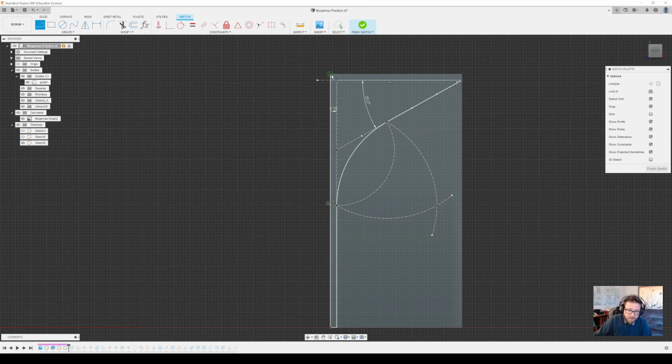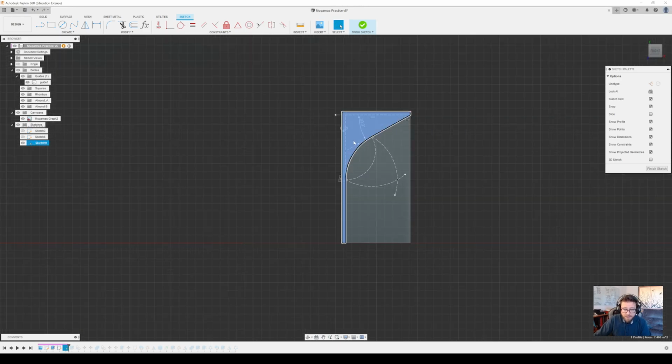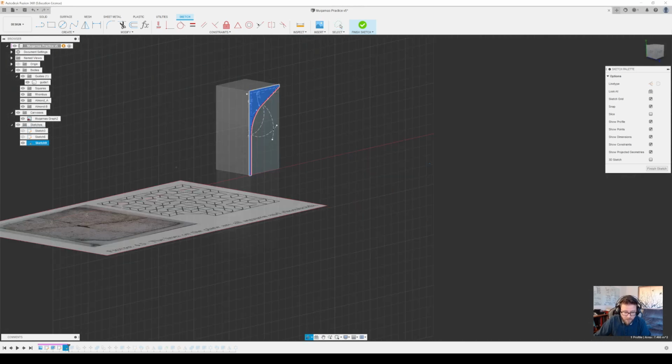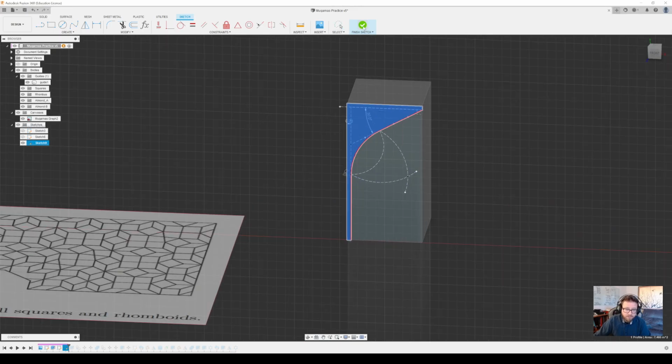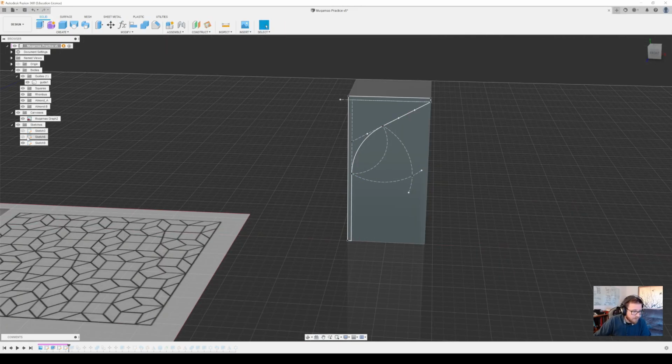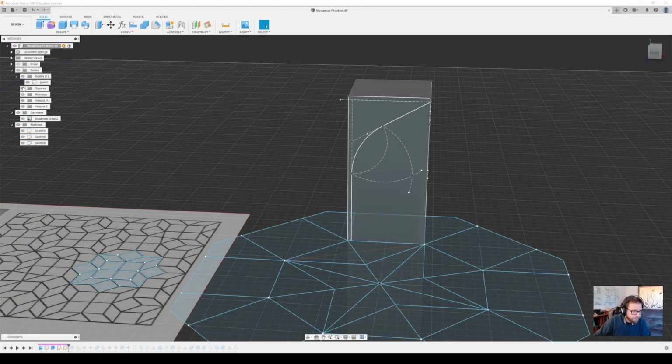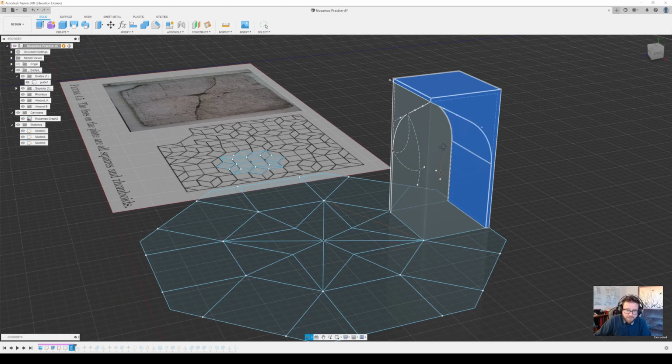is going to be a solid line, which actually separates, as we remember from before, these parts into separate pieces, right? So it's ignoring those dotted lines, okay? And that's all we need. So from there, this one example that we've got right here is all I needed to do to create that. So I'm going to hit Finish Sketch here. I'm going to turn that particular sketch off for now so that I can show off a little bit as we roll through the document.